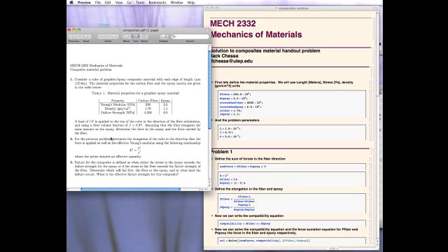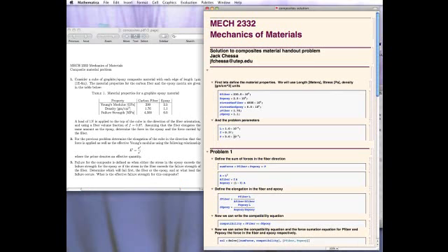Okay, so I first did this problem with the 1 Newton force. That was a little high. You get the same answers with 1 Newton or a smaller force, but when you use the 1 Newton force, you get very large stresses and very large strains. They're not really realistic, but since we're doing everything linearly, it's fine. I'm going to change a little bit. I'm going to use 5 times 10 to the 3rd newtons as the force, okay? And you'll see why in a second, but it goes the same way.